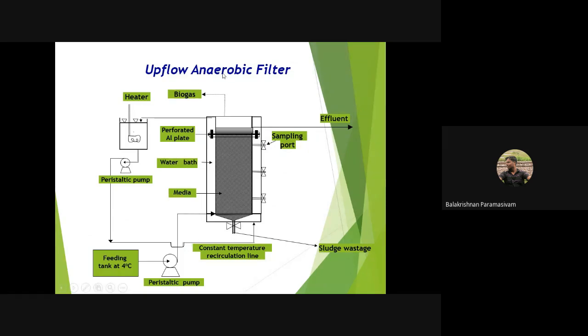Generally, in an anaerobic treatment filter we need to maintain a high retention time, high hydraulic retention time. So we will be going for the bottom to top approach only. To give more hydraulic retention time and high sludge retention time, we are going bottom to top. Temperature is one thing. If the temperature is high, the reaction rate will be very high. When the temperature is low, it will affect the reaction rate.